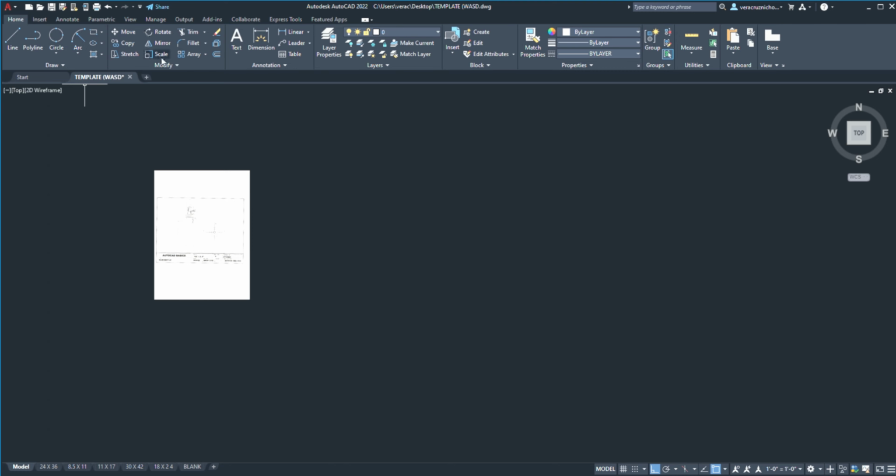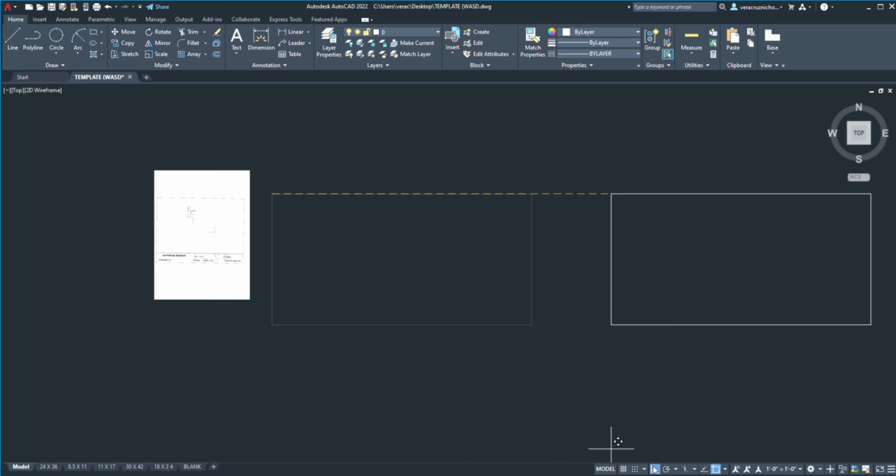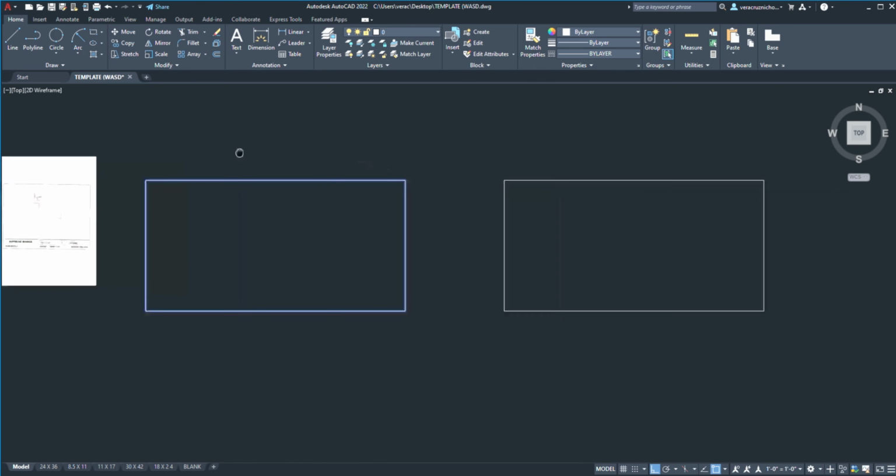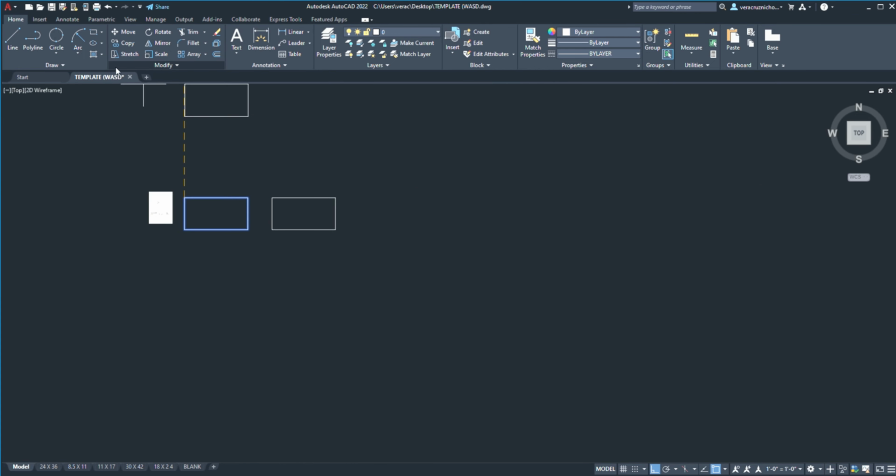We've done drawing, now we're going to do modify. I'm going to need the rectangle again. Move, simple as that. Click from one point, move to another, up, down, other. Removing ortho will let you move freely. Copy, if you want something, you can copy at one point, move it to another. Boom, bang, pow. There you go.